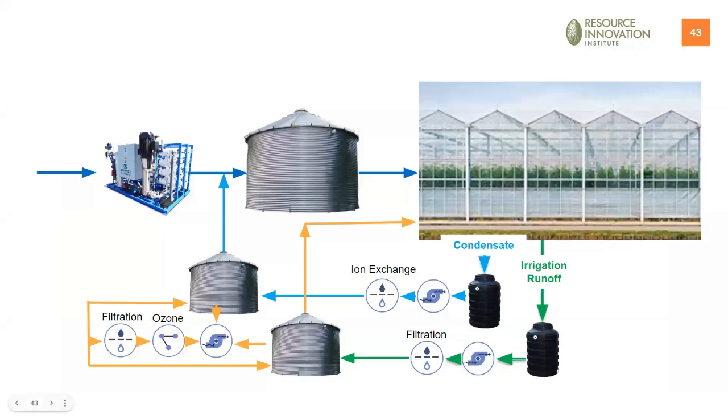Okay, this is the last slide that I'll talk about. And you see I've added to the diagram here where we would recommend adding filtration and the disinfection in this schematic. So if you look at the condensate return line from the sump, you'll have a pump probably at the bottom of the sump.